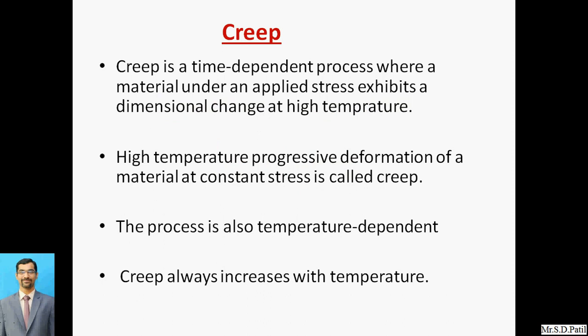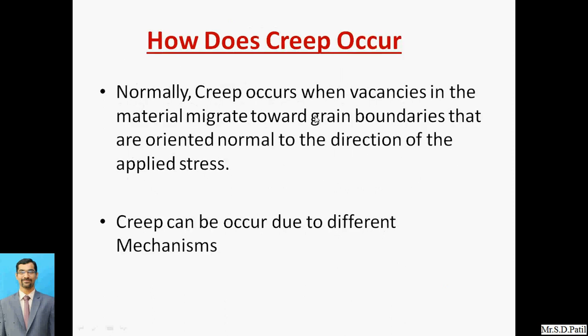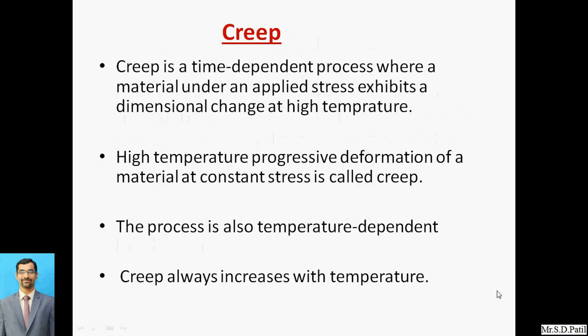So creep is a time dependent process where a material under applied stress exhibits a dimensional change at a high temperature. So this particular term is very important, that is the high temperature. In case of tensile stress, it is again some sort of time dependent process where we are applying the load on that particular component, but that load is not dependent on temperature.